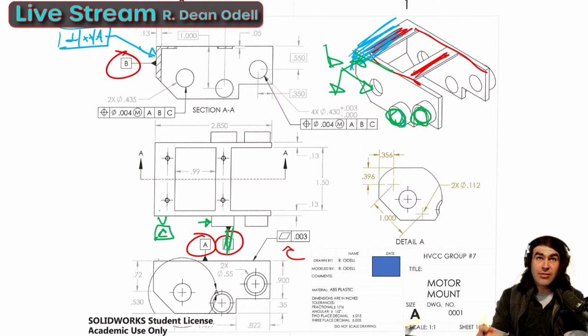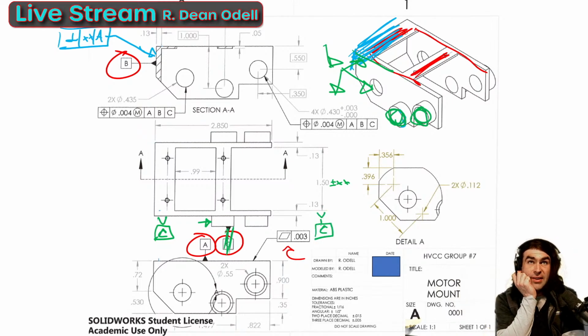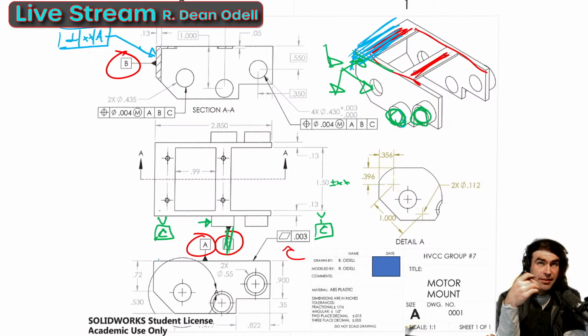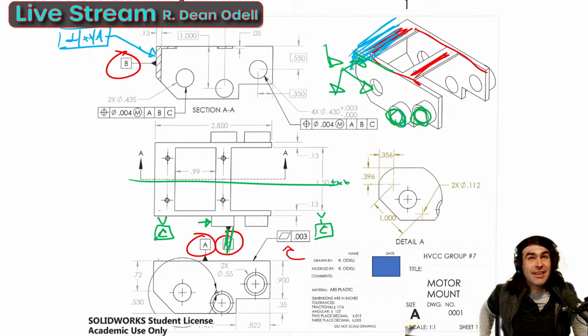Or even consider, since this thing is symmetric, we might want to come in this 1.5 inch, right, and center that dimension. I think making that mid-plane would probably make the most sense. Then that would indicate to anybody dealing with this part that one side doesn't matter more than the other. It could cause some minor inspection headaches, but the design intent is that this is a symmetric part, and making the center of the part datum plane C really gets that across.